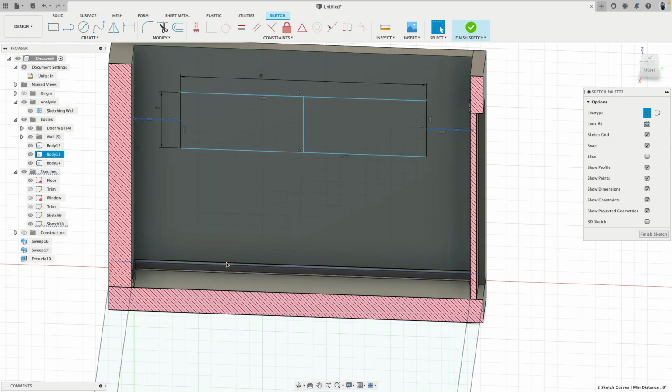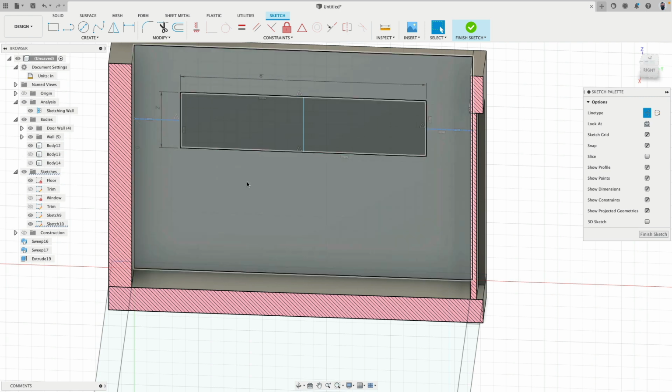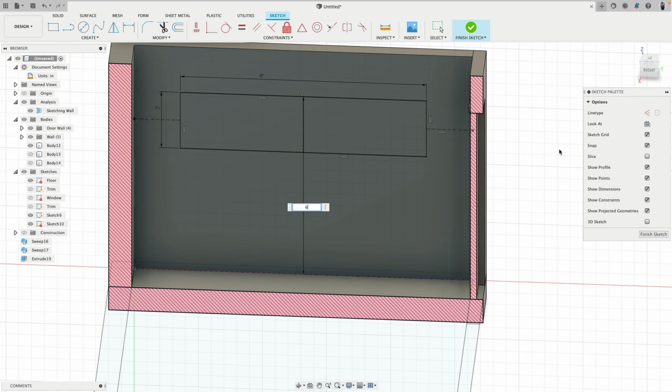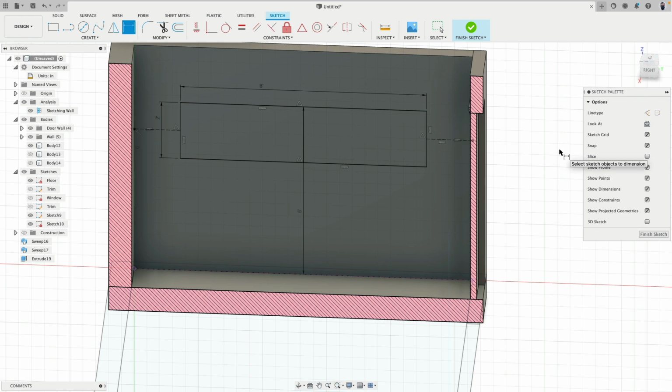Okay, from the ground. This body here, I'm going to hide this one too. So I can go dimension and then say from this point to this edge down here, that should be 6 feet. So now we brought actually this board down exactly to the dimension we need.